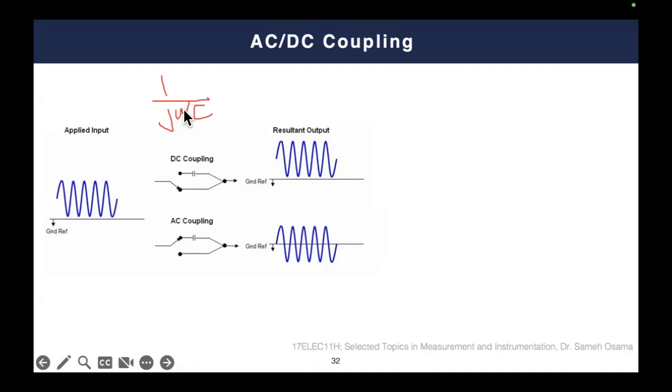Of course, ideally the short circuit condition happens when 1 over j omega C tends to 0. So the higher the frequency you are operating at, the lower this value, which makes it tend to zero, which is the short circuit condition. So when you are operating at relatively high frequencies, for example megahertz or tens of megahertz, you will see no effect from these capacitances in the AC operation, because simply the term 1 over j omega C tends to 0.